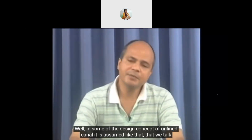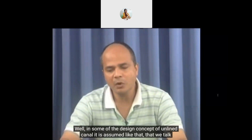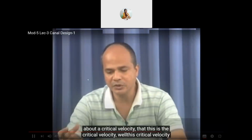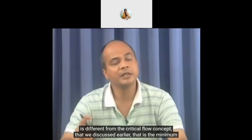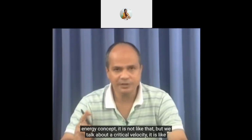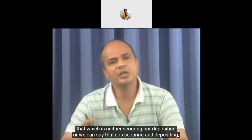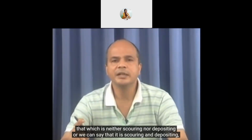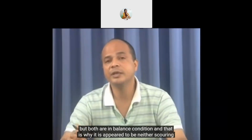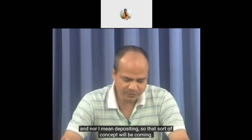Well, in some of the design concepts of unlined canal, it is assumed that we talk about a critical velocity. This critical velocity is different from the critical flow concept that we discussed earlier, that is the minimum energy concept. It is not like that. But we talk about a critical velocity which is neither scouring nor depositing. Or we can say that it is scouring and depositing, but both are in balanced condition, and that's why it appears to be neither scouring nor depositing. So that sort of concept will be coming.